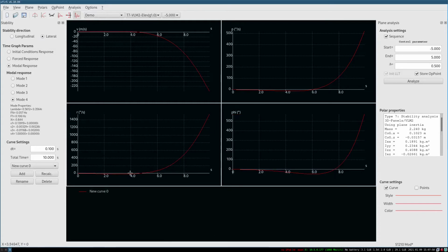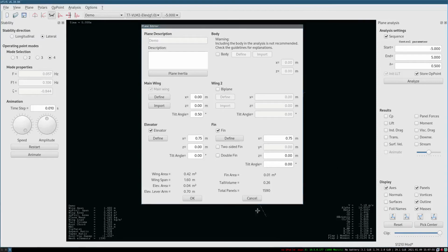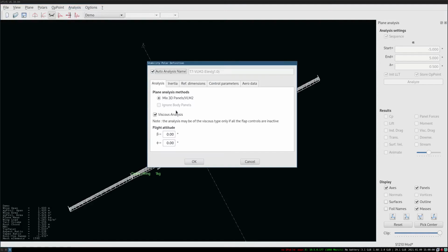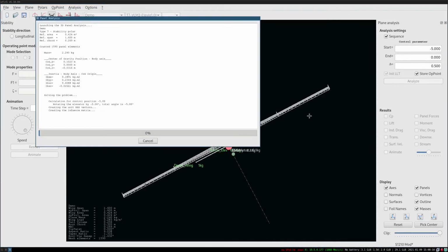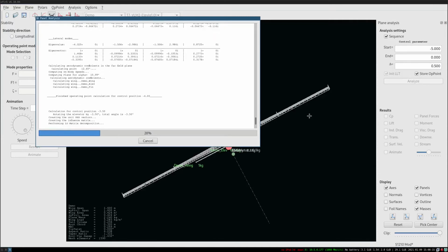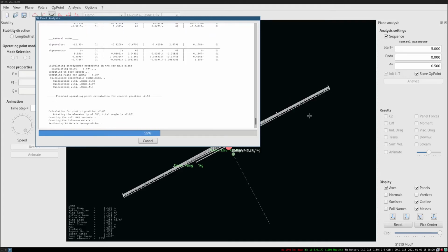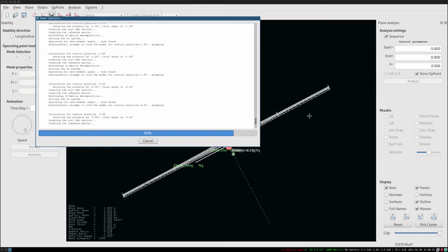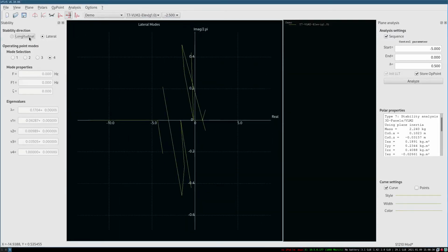Yeah, this is a very interesting mode, quite complex, and I think what this comes down to in this case is we should not have done this. We should remove the tilt angle from the tail and then rerun our stability analysis, which we have to redefine. Again, highly annoying. I think it was 0, I think it's what we ran. I think it's the ones that give us good, valid data, i.e. trying to pitch the nose up, which makes perfect sense considering that the centre of gravity is forwards of the quarter chord. We have a nose-heavy aircraft, and as the adage goes, nose-heavy aircraft fly badly, tail-heavy aircraft fly once. Now that done, we should have some somewhat cleaner plots.